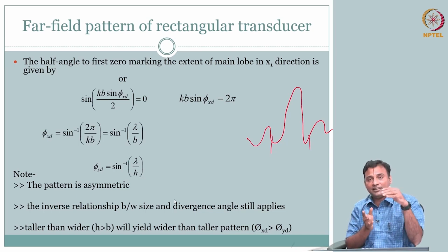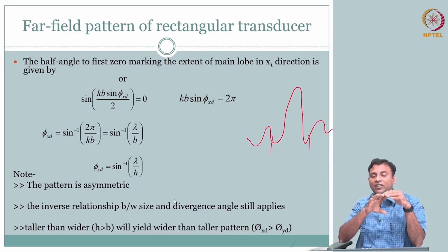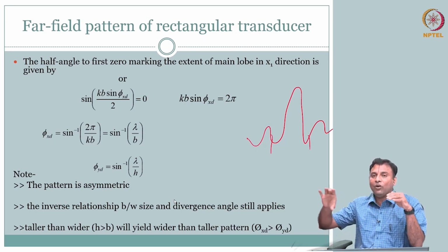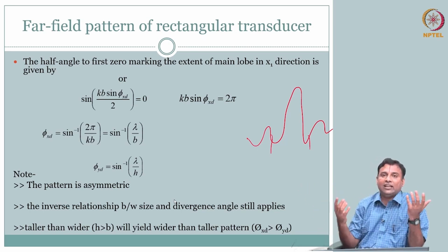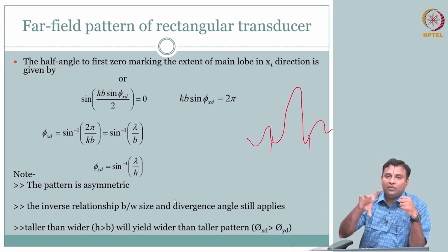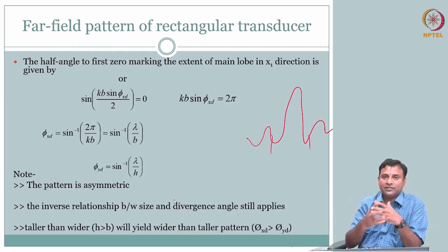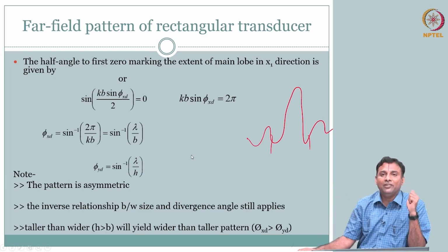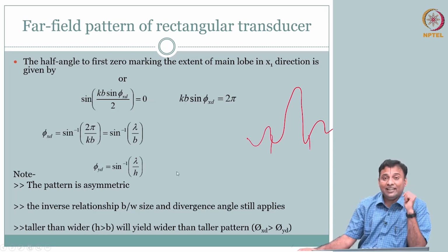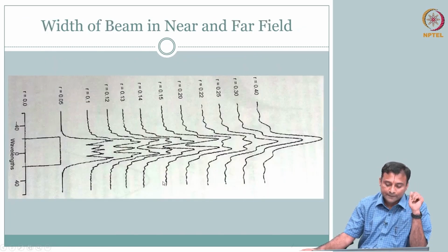But if I go for a larger aperture, then even if it is not diverging, the volume that it is going to insonify is already large. So, you will get a signal from a large volume which is integrated, and you get one value. So, in some sense there is a trade off. We will explicitly cover that as we go forward.